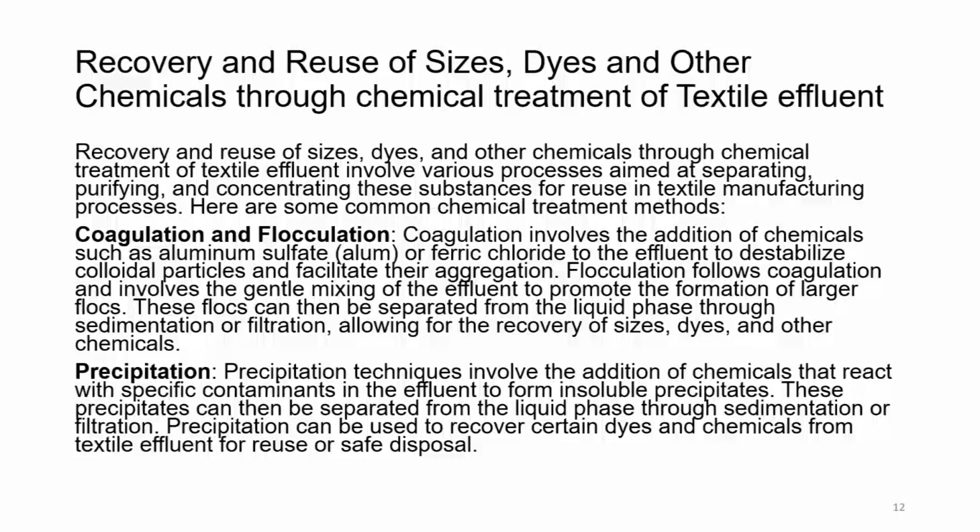First, suspended solids, a coagulant like alum or ferric chloride is added and gently it is mixed, and then it is allowed to settle so that the suspended particles, the colloidal particles, can all come together and form flocks, and then these flocks become heavy, so they settle down. They can then be separated by the filtration process.